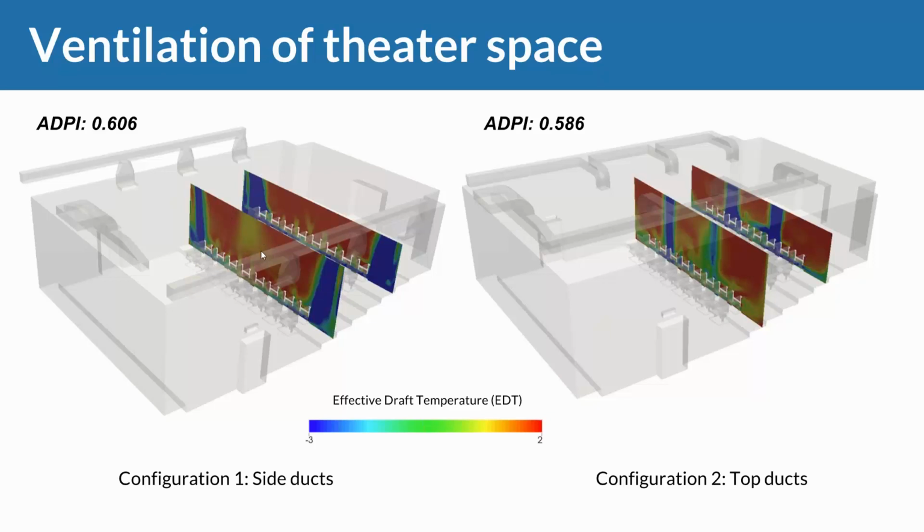While in the middle, that is largely red, and I have excluded these slides that make this an even more quantitative approach, so you could go really down to each seat and predict per seat how many seats would feel comfortable in both of these scenarios, right? So that's something you could dig deeper into, but I didn't want to spend too much time diving through that. Also at the top, you can see the ADPI value. That's an indication of how long it takes to exchange the entire air in the room. That's also oftentimes relevant to many customers we're seeing using CFD in building design.